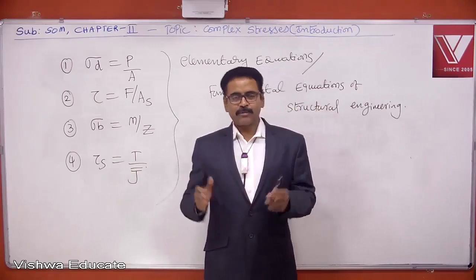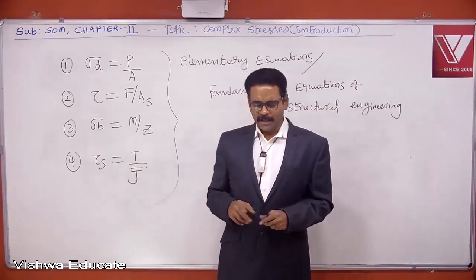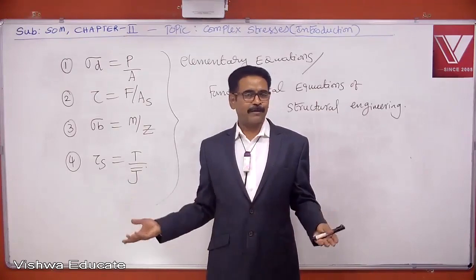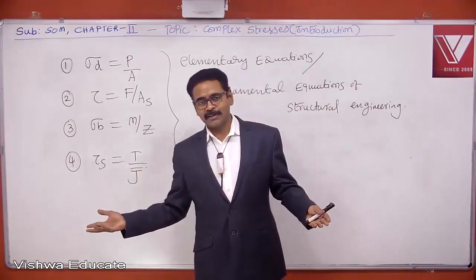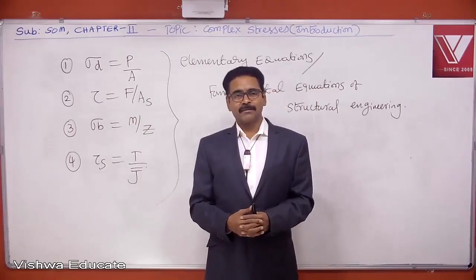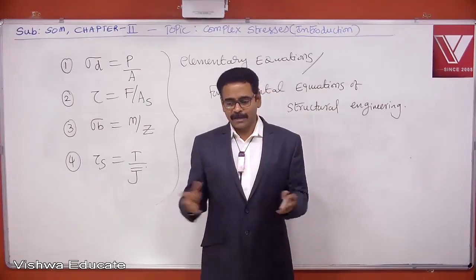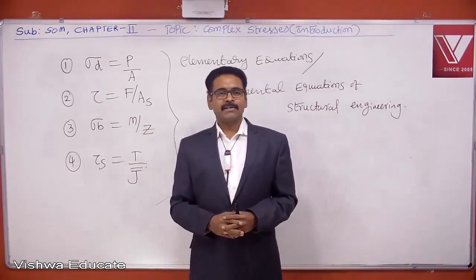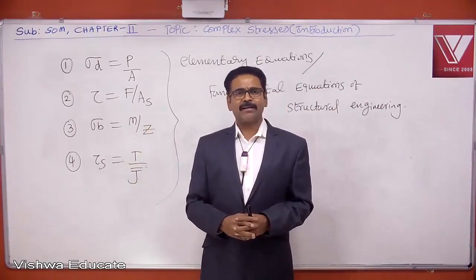These two parameters are very important. If major principal stress is less than strength, no problem, man. If major principal stress is approaching strength, then at any moment of time, structure may fail. Similarly, about which plane do brittle structures fail? Brittle structures fail about major principal plane.